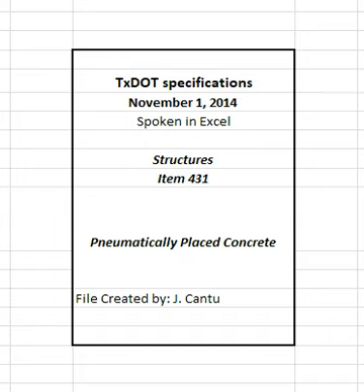3.6 Finish. Use a sharp trowel to cut off all high spots after the concrete has been placed to the desired thickness or screed to a true plane as determined by shooting strips or by the original concrete surface. Lightly apply cutting screeds, where used, to all surfaces so as not to disturb the concrete for an appreciable depth. Work in an upward direction when concrete is applied on vertical surfaces. Give the finished concrete a final flash coat of about 1/8 inch unless directed otherwise. Obtain a uniform appearance on all exposed surfaces unless otherwise shown on the plans.